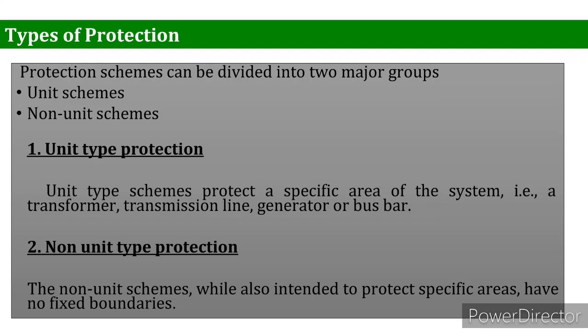And about non-unit type protection, the non-unit schemes, while also intended to protect specific areas, have no fixed boundaries, as well as protecting their own designated areas. The protective zones can overlap in other areas, which can be beneficial for backup purposes.